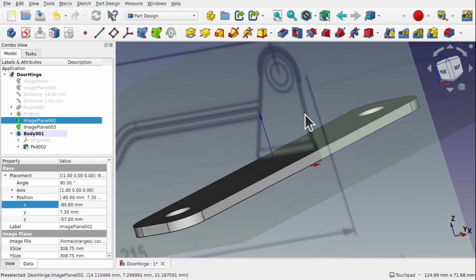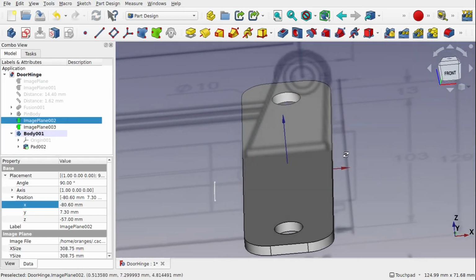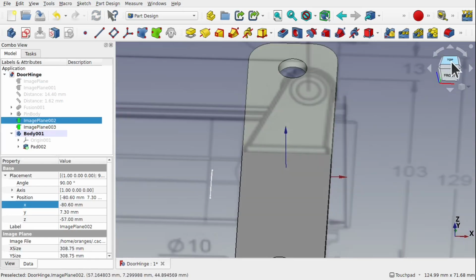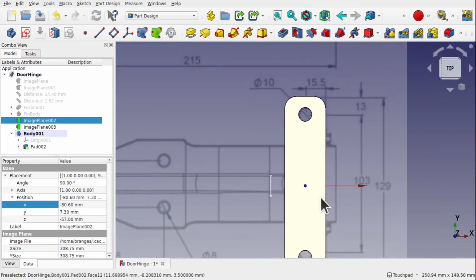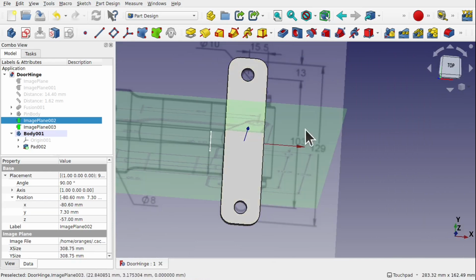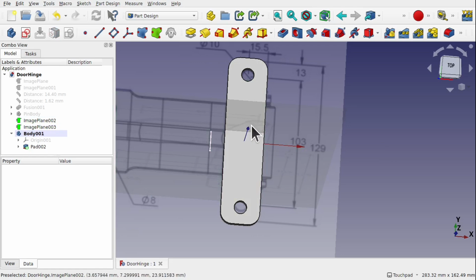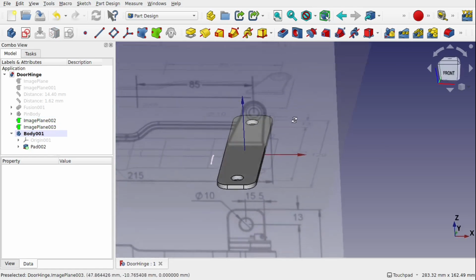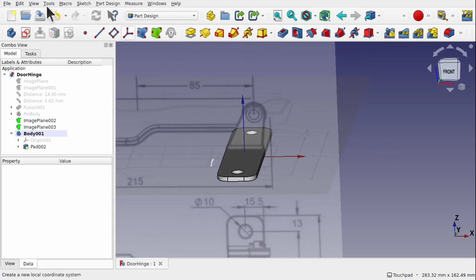Next, let's create this feature. Look at the top and see where it's going to sit. So it's going to sit in here somewhere. As said, there are multiple ways of creating this feature. I'm going to make sure nothing's selected and sketch it first without selecting any geometry for reference.